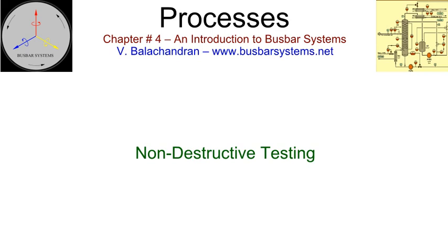Visual examination. A visual examination by a trained inspector is the most cost-effective way of carrying out this activity. But it can only recognize the surface defects that are visible and draw subsequent inferences. For internal quality and defects, other types of tests are required for certification. Surface crack detection: dye penetrant test, DPT, and magnetic particle test, MPT, are the most common testing procedures followed for the detection of surface cracks.